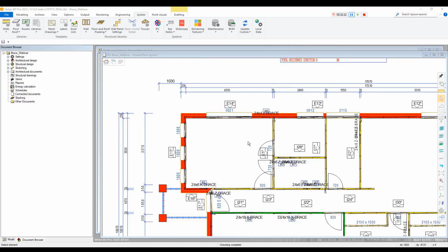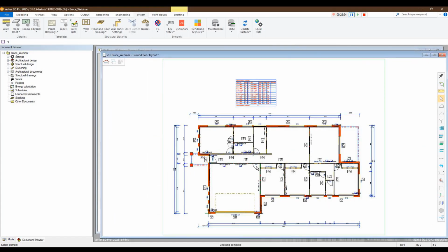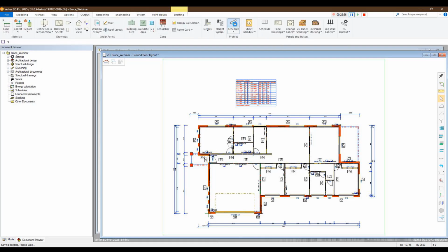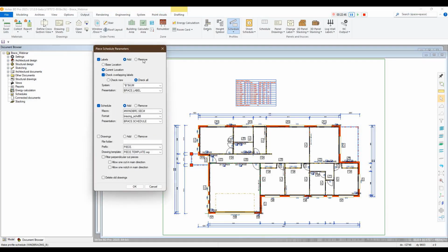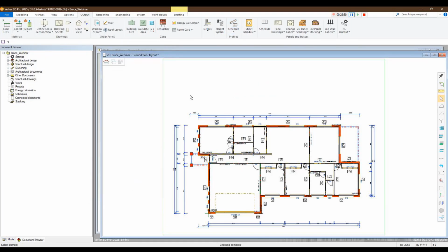Now, one thing that we have to do, if you are looking at now using these new load tables, is activate those load tables so that they can be used. So first thing I'm going to do is just remove this schedule. If you go back to your output tab into schedule, and this was in the B direction, I can just click on remove, and that will just remove all of my setups.